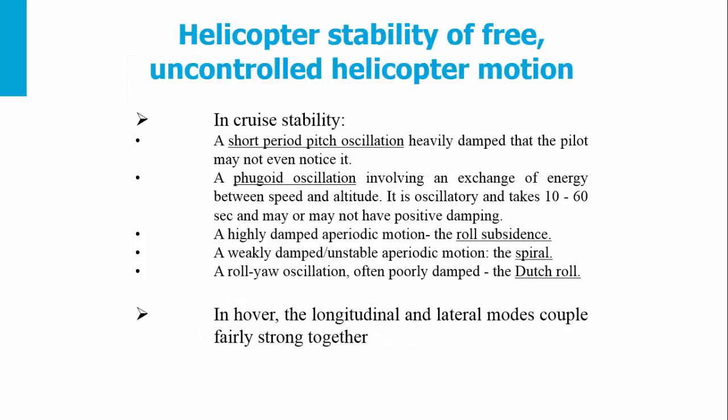Now, if you recall all these lateral modes, and if you recall as well the longitudinal modes, it means that the helicopter stability of free motion involves actually a short period pitch oscillation, which is heavily damped so that the pilot may not even notice it, and a phugoid oscillation, which is actually an exchange of energy between speed and altitude.